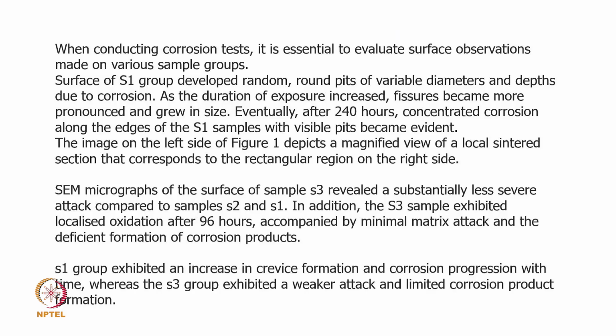If I want to express in my words, I will say that when conducting a corrosion test, it is essential to evaluate the surface profile, or rather metallography. That will give a better understanding. We could see that the surface of the S1 group developed random, round pits.